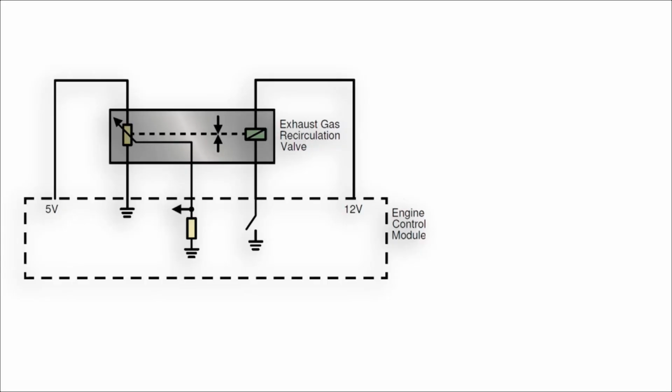The mass airflow sensor should now see a reduction in airflow due to the incoming EGR gases. If there is no reduction in airflow, then the butterfly will close more and the EGR will be opened more. This process will continue until the ECM decides that there must be a fault in the EGR system. A DTC will then be logged.